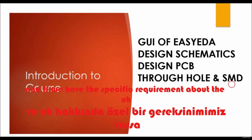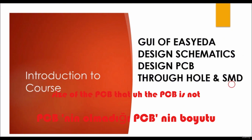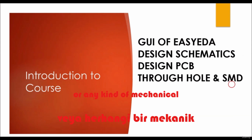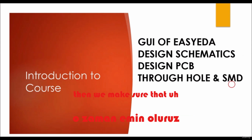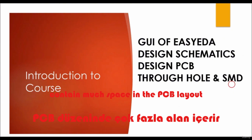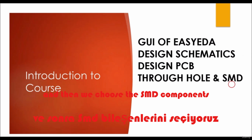And if we have a specific requirement about the size of the PCB, for example the PCB is supposed to fit in any kind of enclosure or any kind of mechanical design, then we make sure that our components are SMD so that they don't take much space in the PCB layout, and then we choose the SMD components.